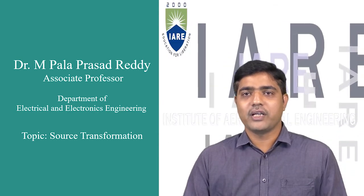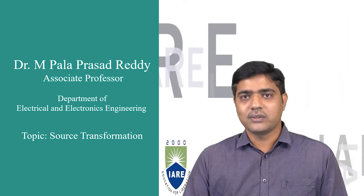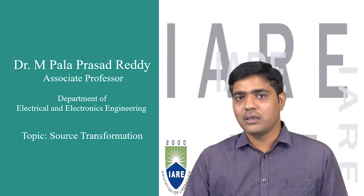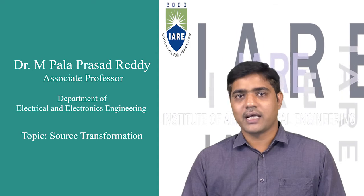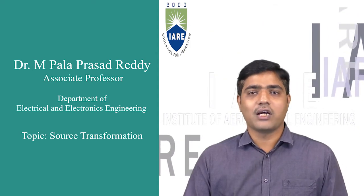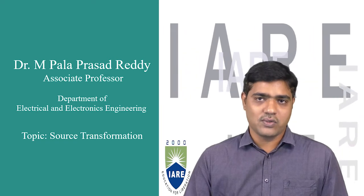In today's lecture, I am going to discuss source transformation technique. So basically, where do you require the source transformation techniques? In electrical circuits, if you are going to solve complex circuits and if the circuits have a larger number of sources like voltage sources or current sources, you may need to convert a voltage source into a current source or a current source into a voltage source for simplification of the electric circuits.